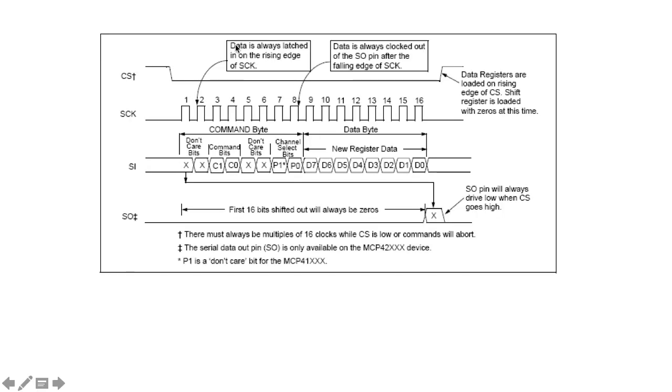So if data is latched on the rising edge, and you can change how that works by using the serial control register, you can effectively determine exactly when the input signal is going to be sampled.